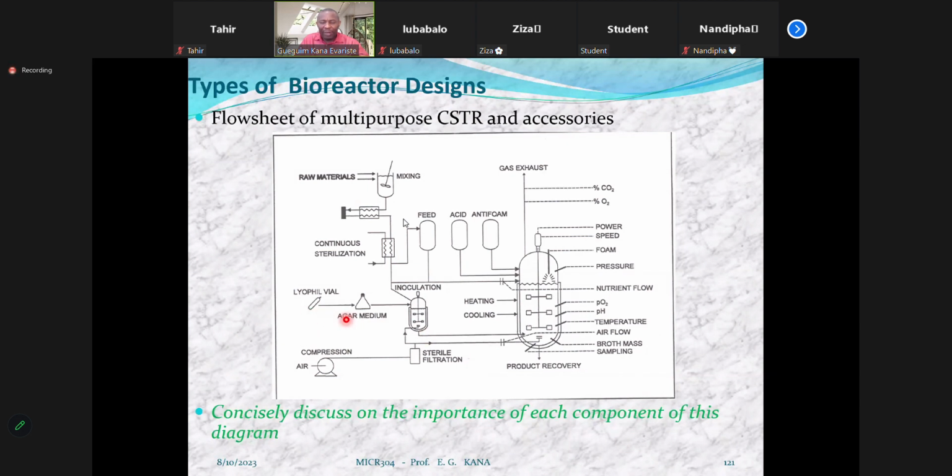Now, during the production of biohydrogen, the source of inoculum sometimes is heated up. Okay? Sometimes they will heat it up, sometimes even to 100 degrees. The purpose of doing that is not to sterilize the inoculum. The purpose why they are heating up the source of inoculum to 100 degrees is to remove other microorganisms that are not involved in the production of hydrogen.